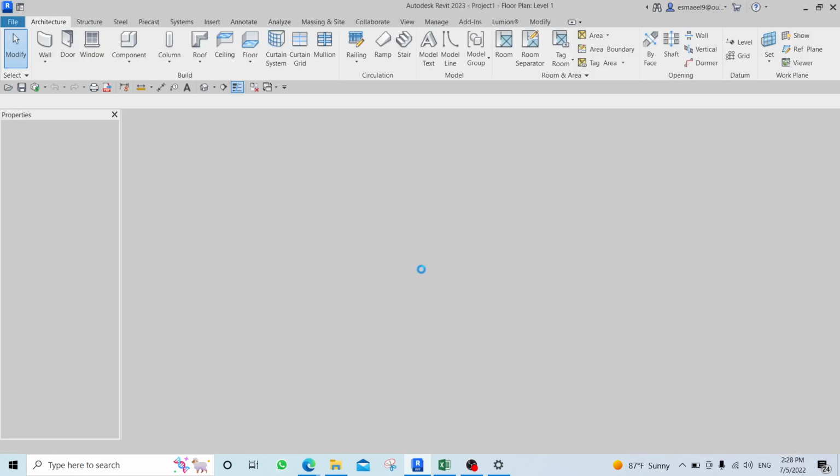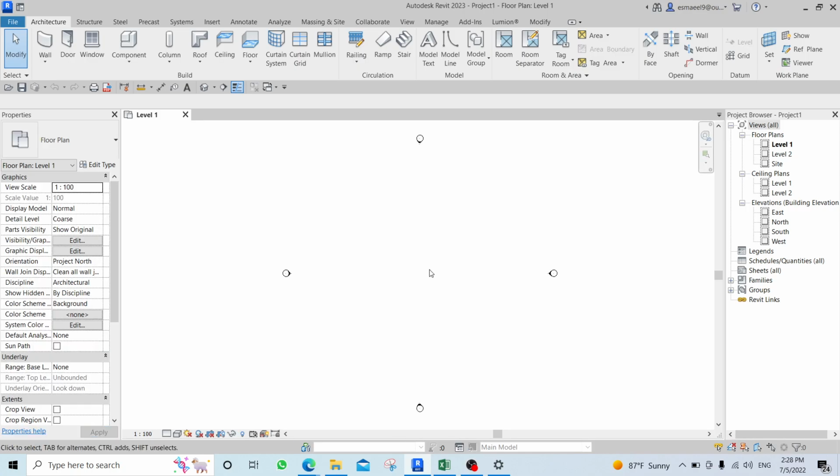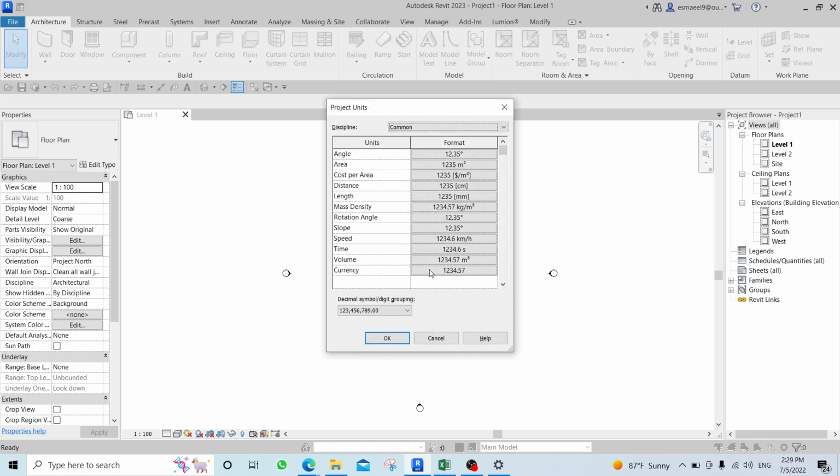and then click OK. The second step of any project is just to click UN. UN is the unit of your project. So we do have some basic beginning steps which you should do, which is the architectural metric template, and then to change your unit.